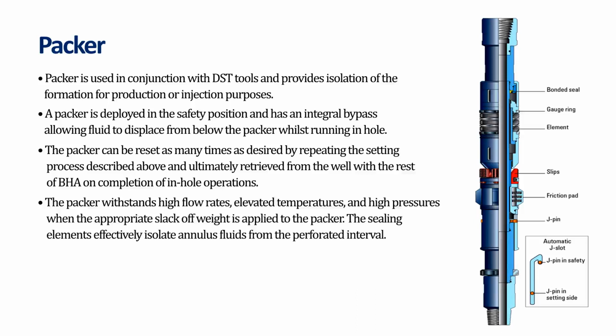The packer withstands high flow rates, elevated temperatures, and high pressures when the appropriate slack-off weight is applied to the packer. The sealing elements effectively isolate annulus fluids from the perforated interval. Let us see a diagrammatic representation of the packer.